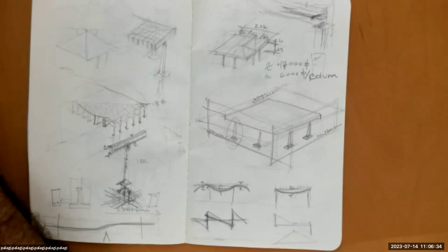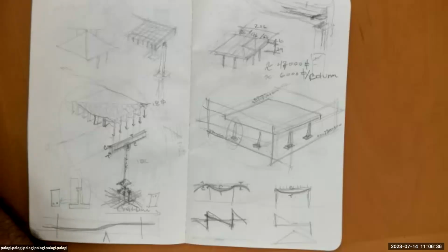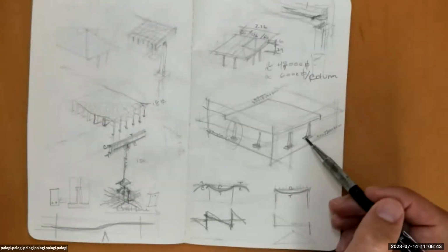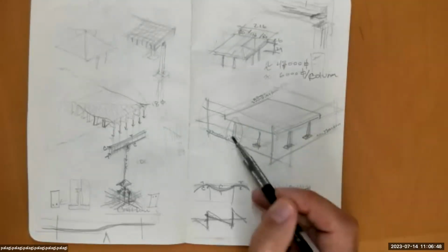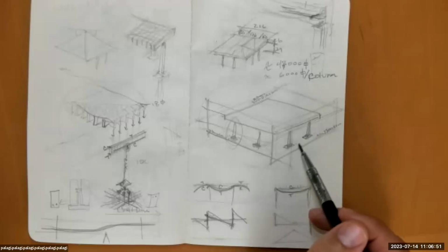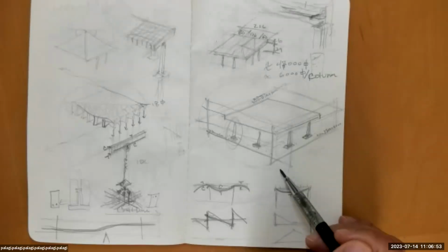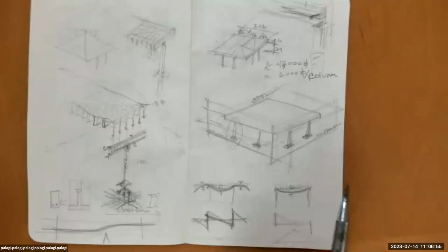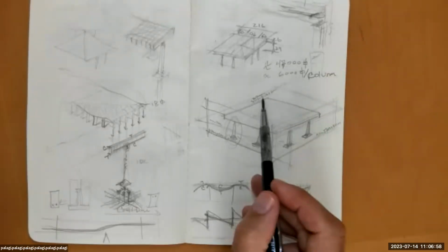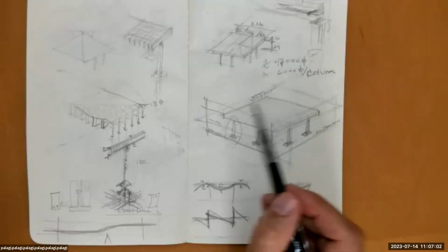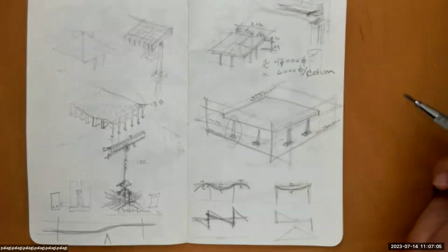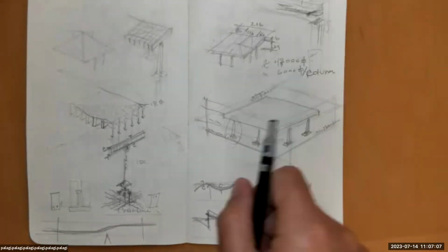X-bracing is either compression or tension. We'll look at that differently in some stuff. Either way, it's just the idea that it's being braced, right? So in this one, we have the moment connection here, moment connection here, right? The base of all those columns is what's resisting the forces this way or this way. In this plane, we have that shear diaphragm, not a shear wall, but we call it shear diaphragm, so we know we're talking about the horizontal plane. Floor diaphragms or roof diaphragms, same thing.